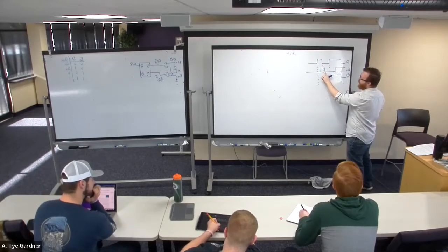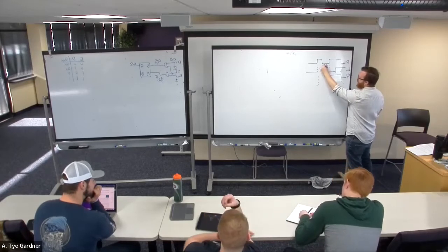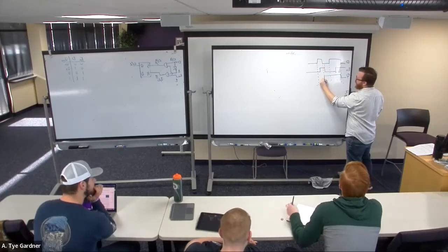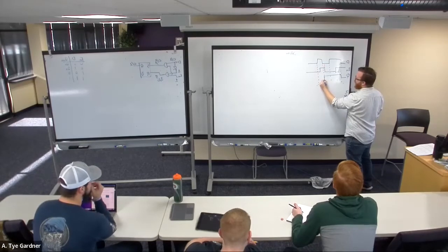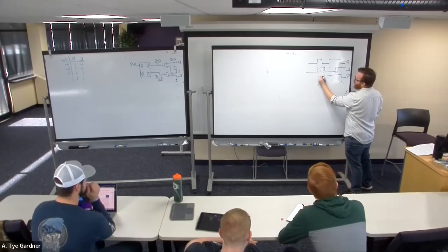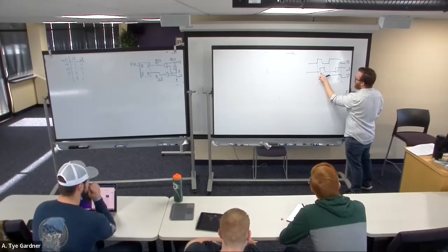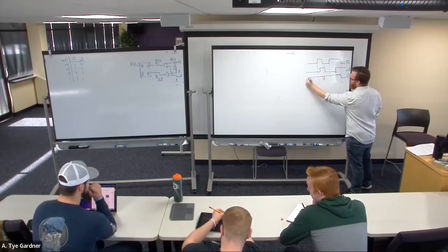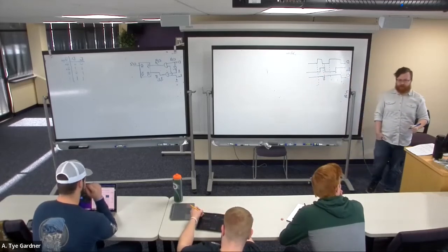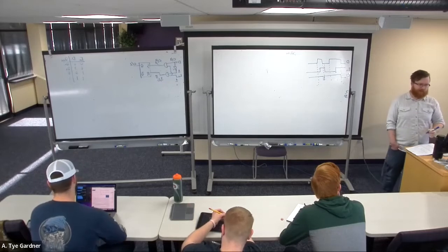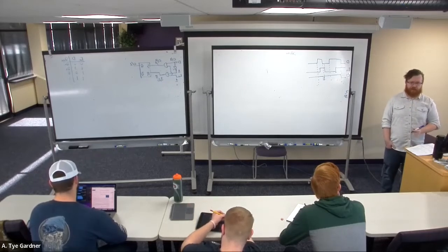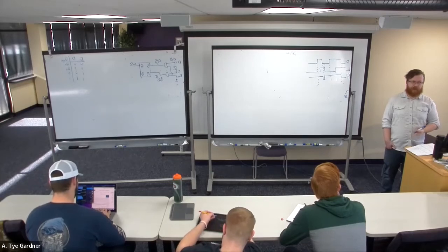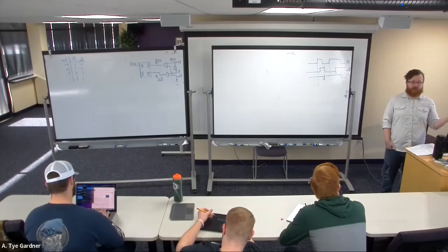Well, now the enable turns on here, which means it's going to get a little blip of a 0 before the D pops back up, starts coming over, the enable turns off. Doesn't matter that the D changed. So I'm just looking at follow D. Q follows D when enable is true, otherwise holds its value.